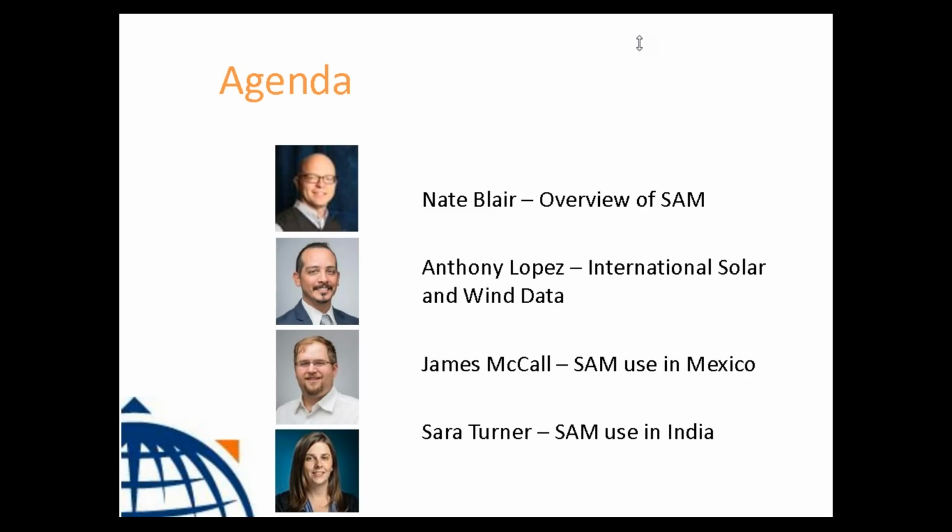Question: could you please tell me if I can use SAM for a hybrid system, for example, PV plus a generator in isolated sites? That's an interesting question. Basically the answer is no. SAM is not typically what you would go to for a microgrid type analysis of a PV and a generator. What some people have done is, for the same location, set up a PV system as one case in SAM and a wind system as another case. Then you would have to post-process and add those technology outputs together, and the net would have to come from a generator. So you could see how you could do that, but again, that's after the fact, or post-processing in SAM.